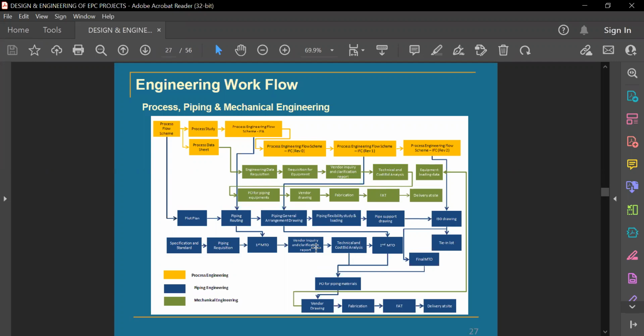Then I have to have a cable for that, bearing temperature or winding temperature or any other thing. I cannot leave that, it is my job. But as a complete package we have to see it from every perspective. So every item will be checked by all the respective disciplines. We call that interdisciplinary check, IDC.